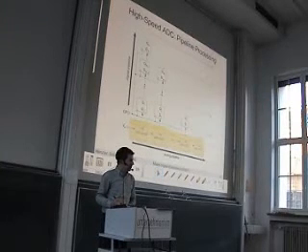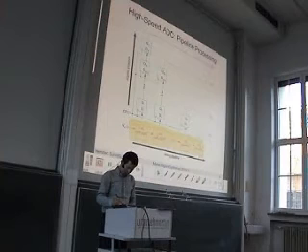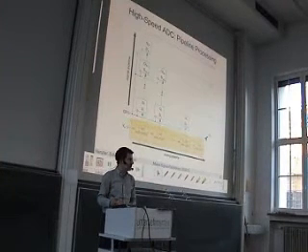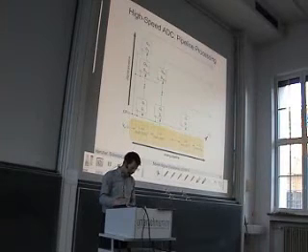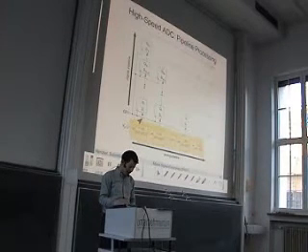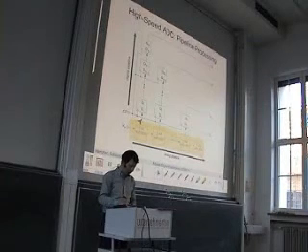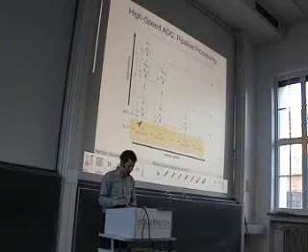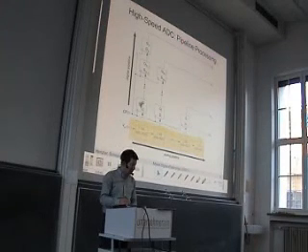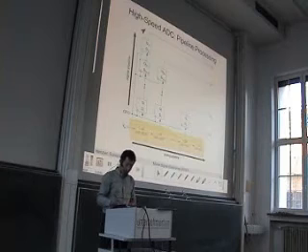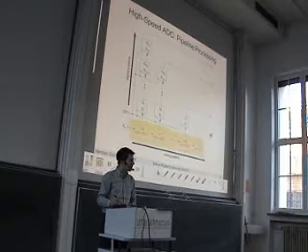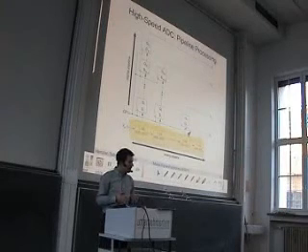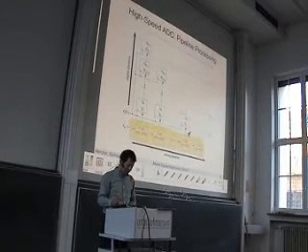After n cycles, the LSB of a certain sample comes out of the pipeline. However, the MSB of this conversion is valid even n cycles in advance. So we have to delay the MSB by n cycles in order to align it with the LSB. So for all intermediate bits, we need this aligning and this delaying too.